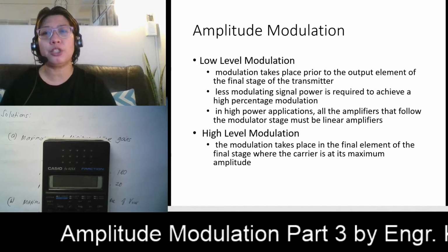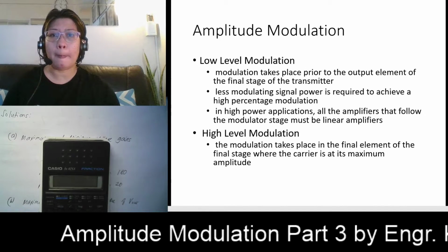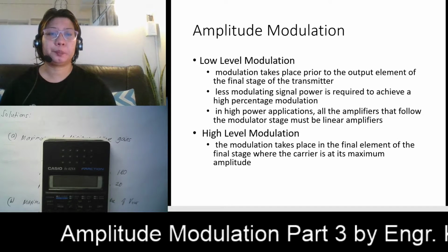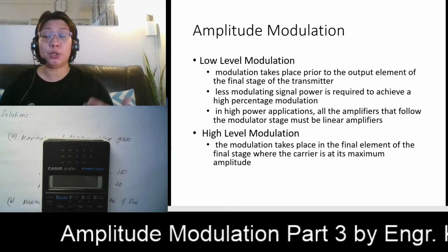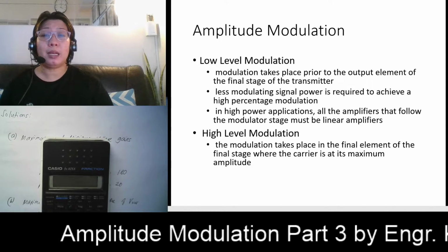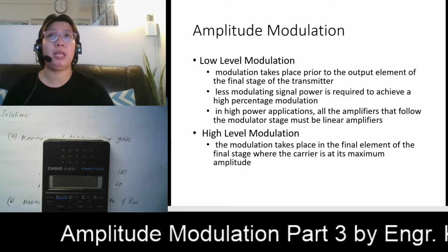It doesn't necessarily mean that low level modulation is a lower type of modulation process, or that high level modulation is a better one. It has nothing to do with that. The thing that differentiates the two is the location in a transmitter where modulation actually takes place.